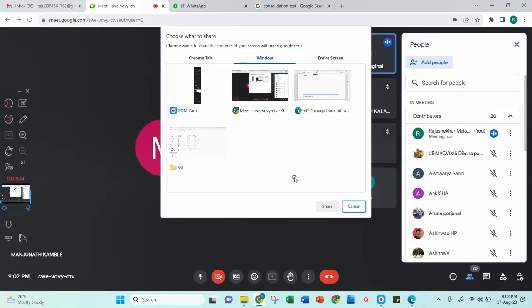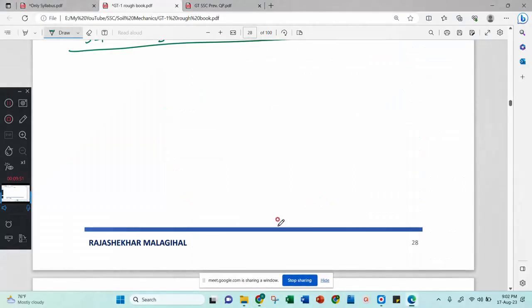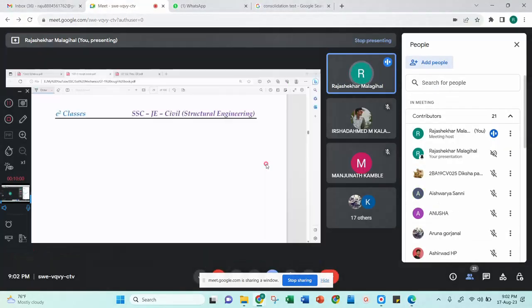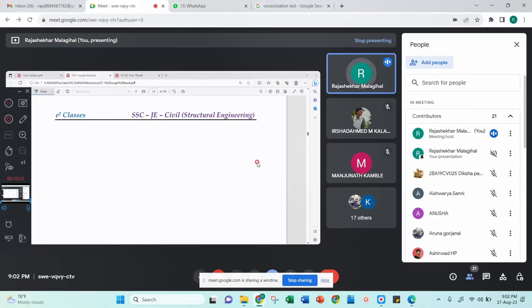Okay, now I will explain the procedure. Sir, the sample is clay soil first? You have to take a clay sample only, because if you take a sand sample, then what happens? Consolidation happens in 5 to 10 minutes. Then why make such a big chapter and study it? That's why, sand has high permeability. Therefore, the water escape will be very quick in sand. That's why the consolidation chapter is not studied for sand soil.